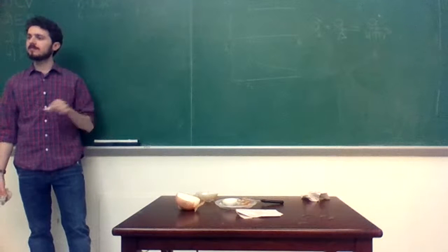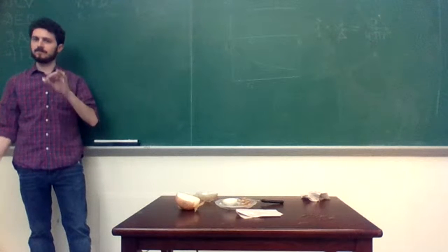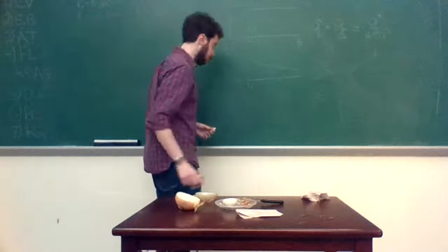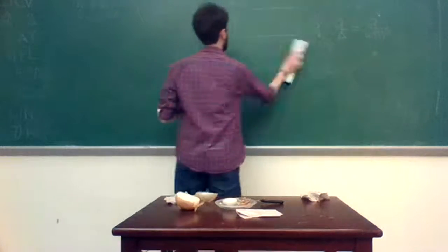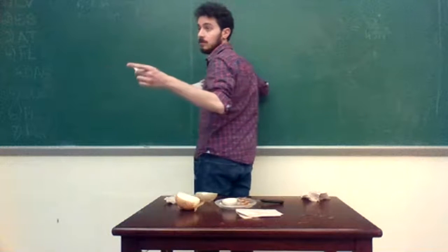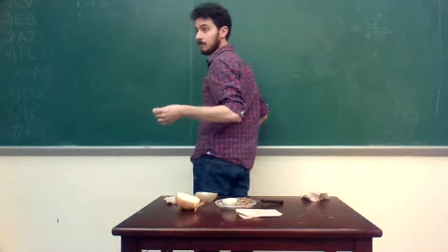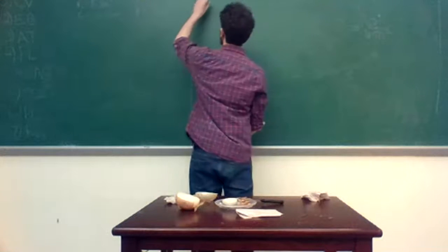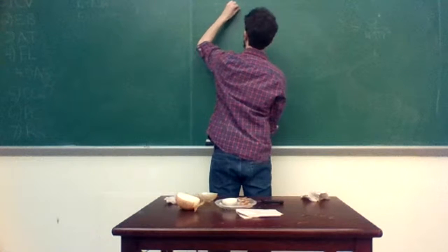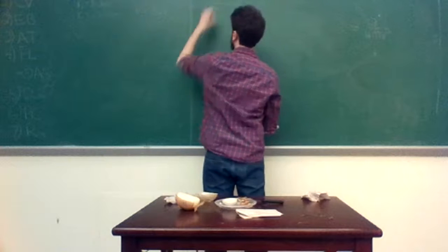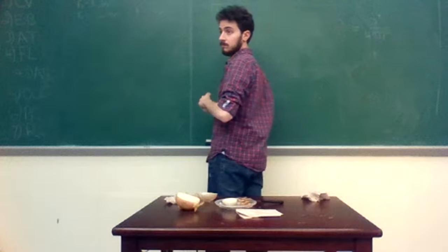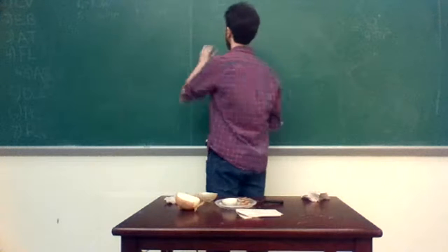Do you guys remember, does anybody have the formula written down for the thermal resistance of a spherical shell? Do we want fresh and dry white onions? Declan, hold on to that for a minute. Is it just like the one that we drew in class? Yeah, our shell. 1 over Ri minus 1 over R naught, and I think that is over 4 pi k. Over 2 pi k? 4 pi k.